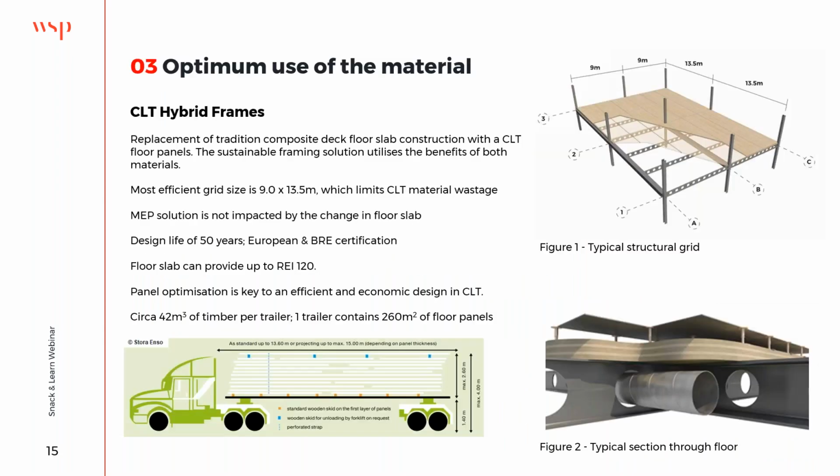So in the UK, in the last couple of years, we saw the use of CLT extremely prevalent in the production of residential apartments up to circa 15 stories. That's probably at the moment about the kind of limitation insurance-wise for the material. However, there were changes in the building regulations due to a catastrophic fire in a building in central London, which meant that you can't build the external facade of a building greater than 18 meters with a combustible material, which meant that we need to think about new uses of this material.